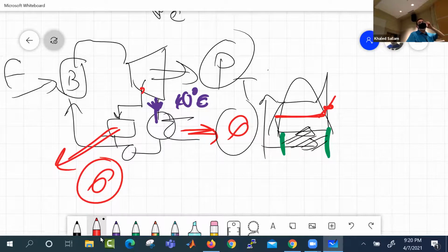But you are getting better heating. So we now just realize that not all Q are created equal. Some Q are better than others, and that is based on their temperature. If you give me 100 joule at 100 degrees C, it is very, very valuable compared to the same 100 joule at 40 degrees. Because 100 joule at 100 degrees C, I can do more useful stuff with it.